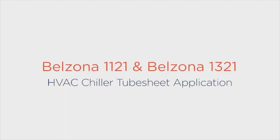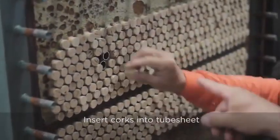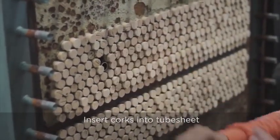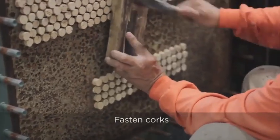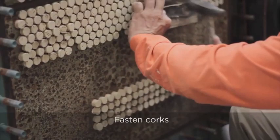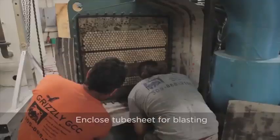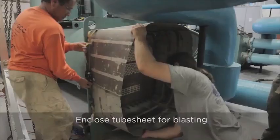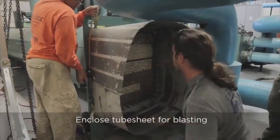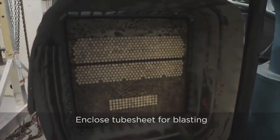Okay, so this is just a quick example of an application we did onto a chiller, a tube sheet application. The first step is always surface preparation. The first thing they're going to do is insert these corks into the tube sheet. What this does is block up the tubes themselves. The whole reason we do that is because we don't want any of the grit from the grit blasting, or any product, going down the tubes because it would block them. And a blocked tube would again reduce the operational efficiency of the system.